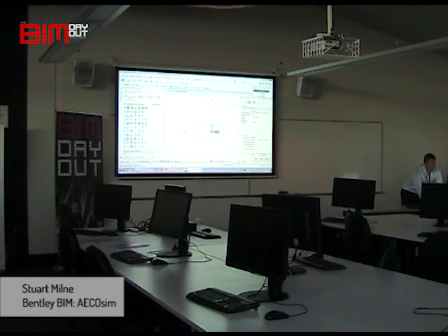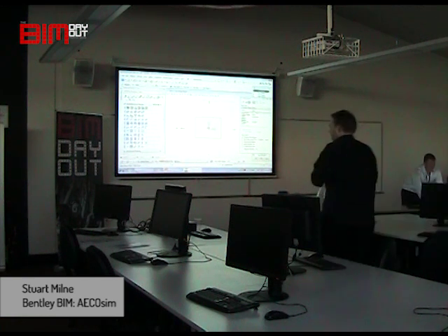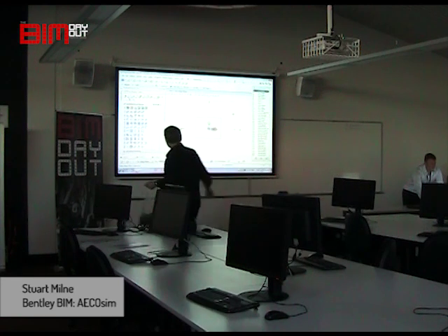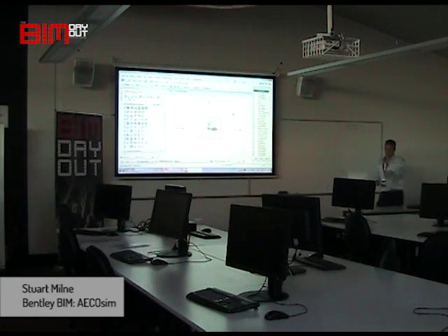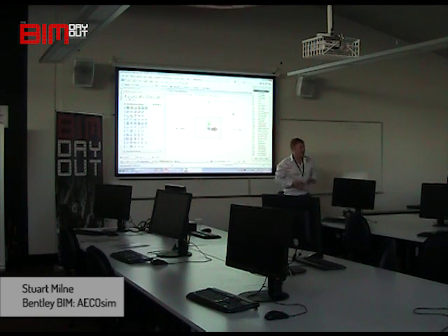Okay guys, so what you've actually done, you've all created a space at the ground floor there. Rather than selecting different floor levels and doing that again as different floors, we'll just copy that one floor up every 3 meters, and then we'll relink each one to the outside of the cube. The easiest way to do that is go to that rotation tool again, hold it down and select front view.